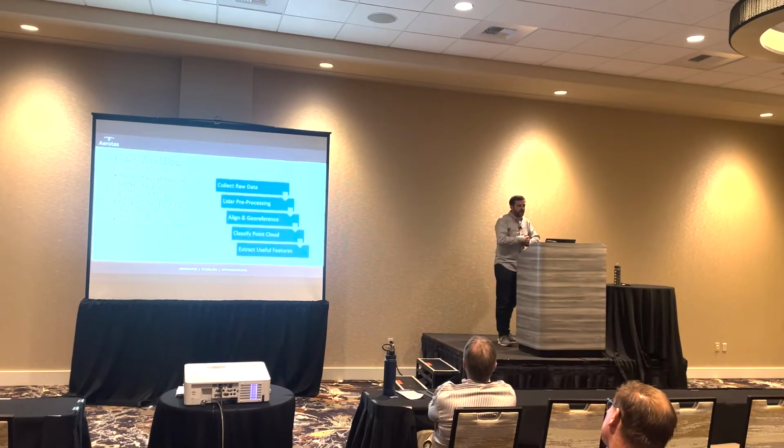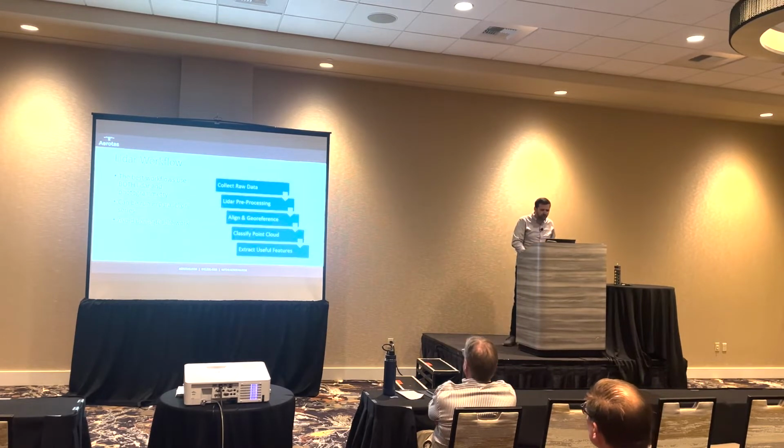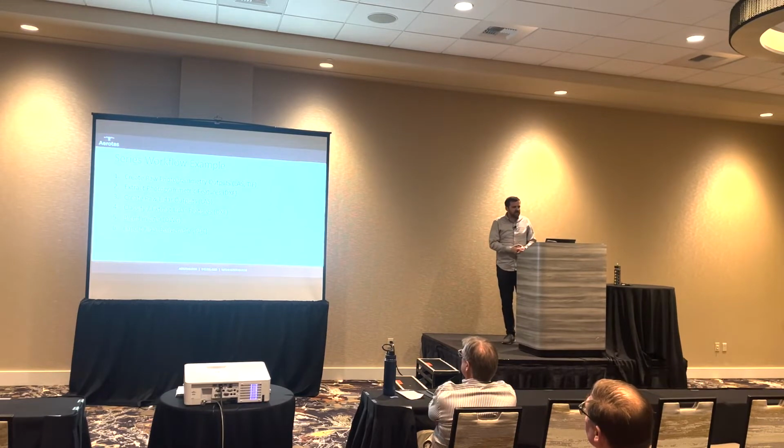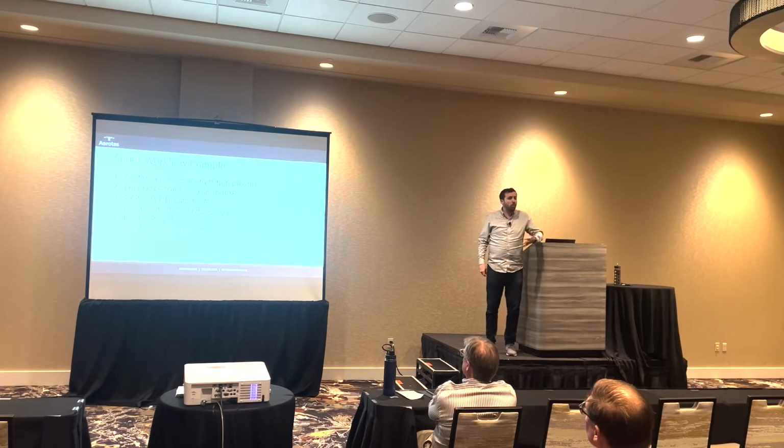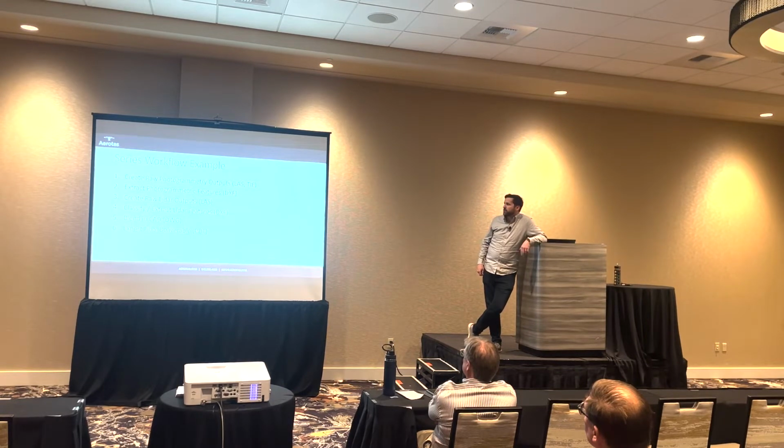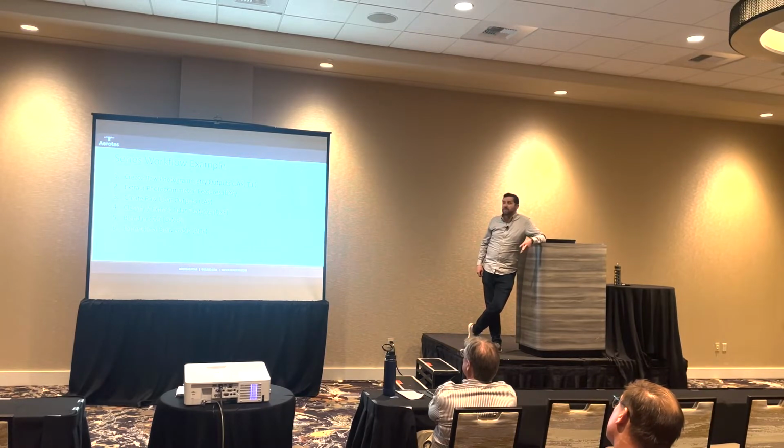These steps are pretty important for us. As far as what the serial workflow example is going to be, this is what a standard workflow would look like if you just have one person that handles most of your data processing. We would recommend starting with all of your photogrammetry outputs, your photogrammetry point clouds and ortho photos, extracting as many features as you can from the photogrammetry point cloud first.